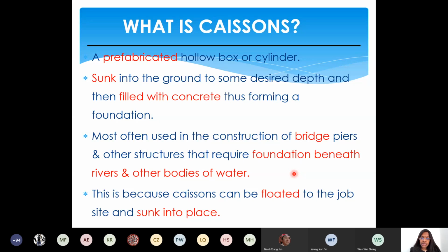Why? Anybody? Can you guess why it has to be caisson type? Because the piers are sitting on the water, there are chances of swaying and chances of erosion, right? All these things will affect only the outer material first. So it will indicate the failure by affecting the outer material. Once it is indicated, you can do some renovation or strengthen the foundation. There are methods of grouting. You can go for grouting and so on, right?